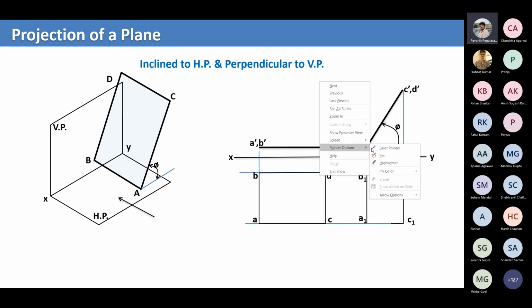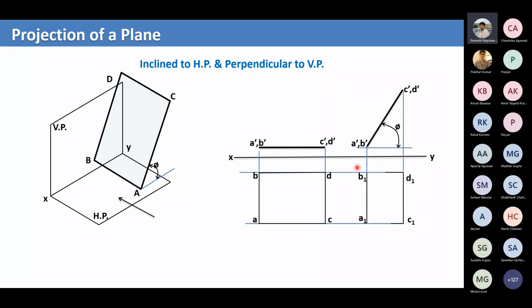Right. I just show you for one of the things. So now you have drawn this construction line here, and you have drawn this construction line. So how do you label? How do you get this as A1 and this as B1? Why not this as A1 and this as B1? So here we are extending the line from BD, and this extension line from BD is meeting the another construction line from AB.